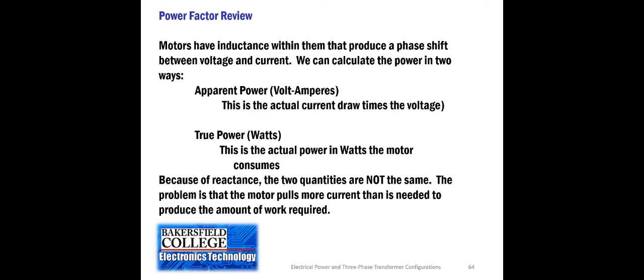If we multiply voltage times current using Watt's law, we have something called the apparent power. If we measure with a watt meter how much power is actually used by the motor, and therefore how much power we're actually purchasing from the utility, then that's true power.